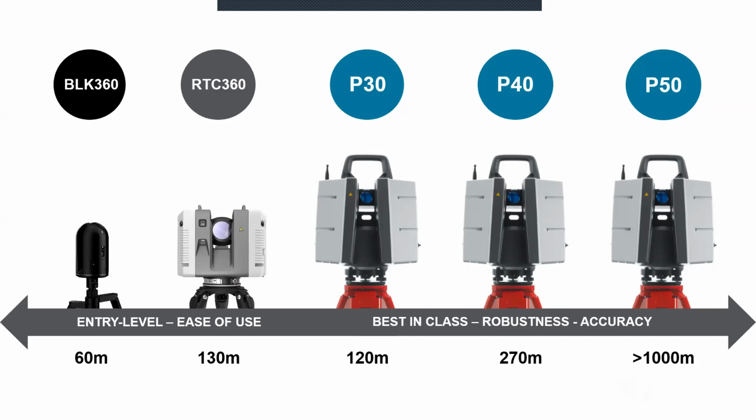Those are around 5.5 kg in weight, so easy to carry, yet most robust, and give you around 5K resolution. It's like a 12 megapixel image capture from a 3 camera system, and in total you get a 432 megapixel image. You'll have 2 million points per second, and it will give you a live update on how the data is getting captured. And when you move the scanner from one position to a different one, it tells you about that.